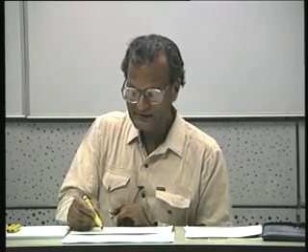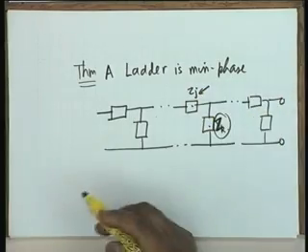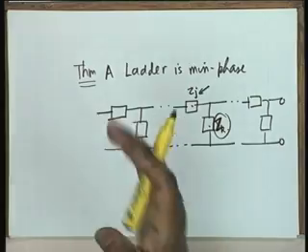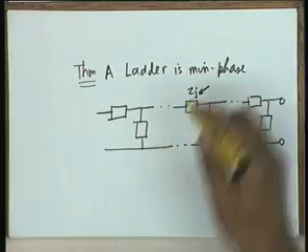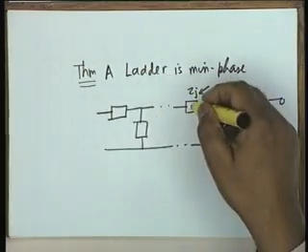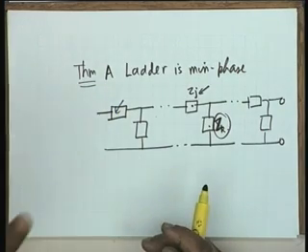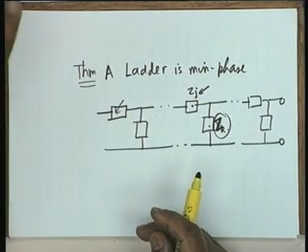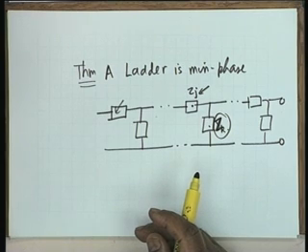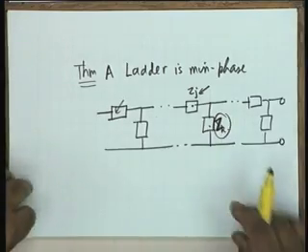Anywhere, because the zero of Zj, any impedance, can be anywhere in the left half S plane. Suppose this pole is shared by another series impedance, then there will be two zeros of transmission at the same frequency. So again, won't there be any division of voltage or sort of stuff? No, they are quite separate from each other.